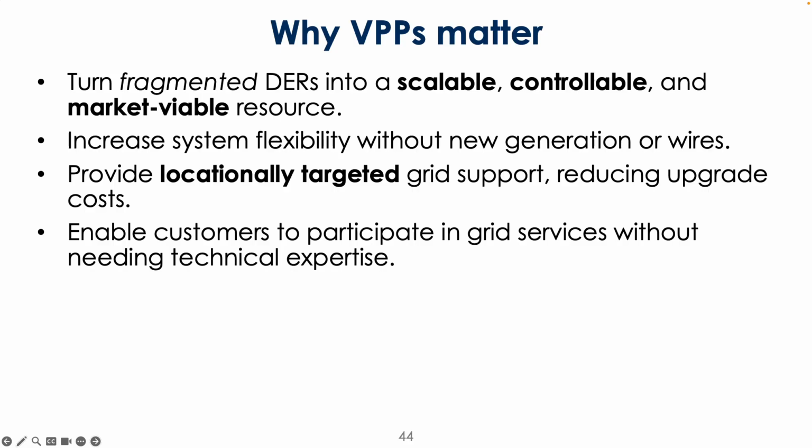And this is a non-wires alternative, right? And so often a lot cheaper. It can provide locationally targeted grid support. We've talked about the benefits and difficulties of providing that support on the distribution side, and the idea is that certain types of VPPs could help with that. And also, I think this is an often overlooked aspect, it enables a customer to participate in a grid service without needing all of this technical expertise, right?